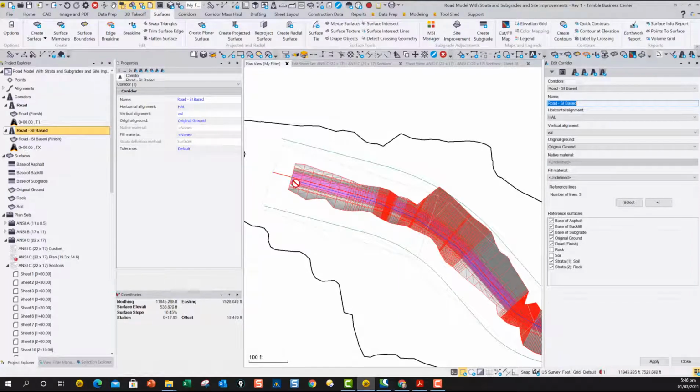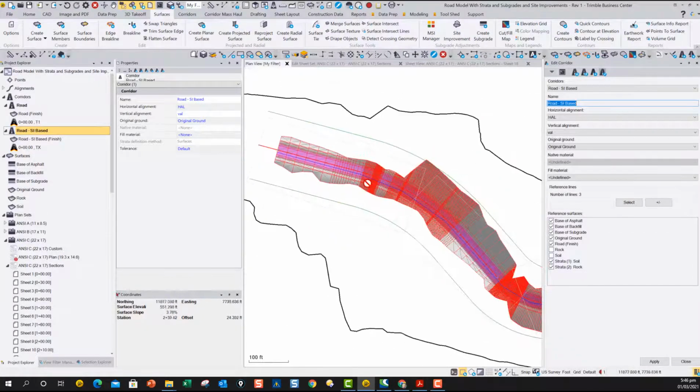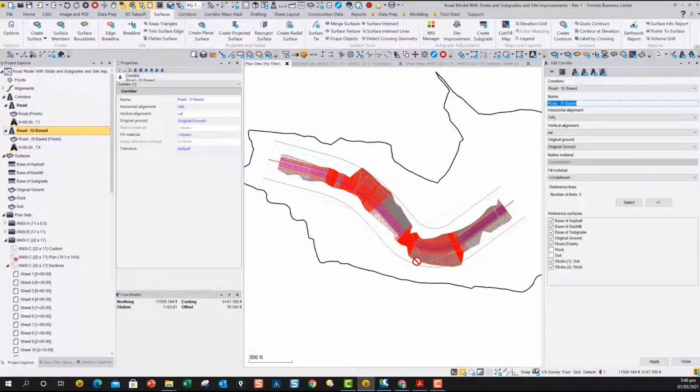And so now, all the way through here, I've got these surfaces referenced. And then I also referenced in the right-of-way lines left and right, and also the storm line, which I've got running down the center line here. This blue line here is a storm line, just to kind of fake up all the things that you might want in a corridor.